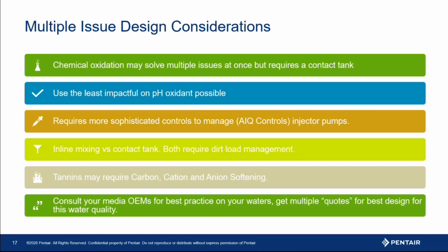Oxidation may break down those tannins in the water and break down some of that organic turbidity, but you're going to need activated carbon to follow up afterwards to clean that up. It may even break down that color where you don't even see it anymore and turn it into more dissolved materials at that point in time, and this may require more sophisticated controls to manage.